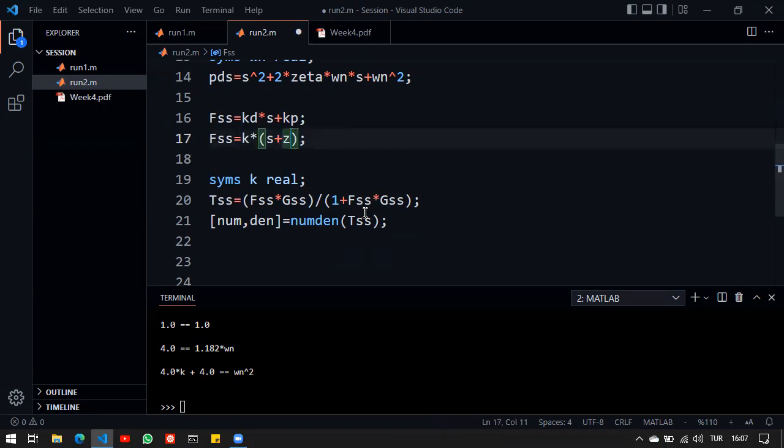And then once I've added this 0 to the system, I can go ahead and design a P-type controller. So that's basically a different approach here. Now, my advice is to always use this form if you're using the algebraic methods, because this will end up in linear coefficients. But here we have multiplications of k and z, and if there are more unknowns, this will be a bigger nightmare in this case.